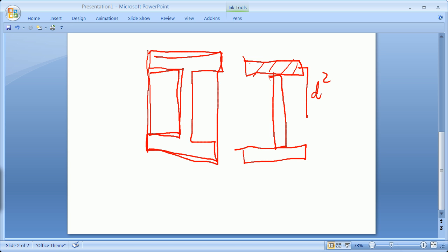What you'll eventually see is sometimes this thing's spinning about itself up here. In other words, this has a height of h and a width of b. As you do your BH cubed over 12, that's really usually often not very much compared to this area, which is b times h times distance squared from the centroid.